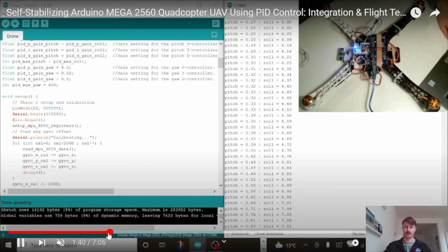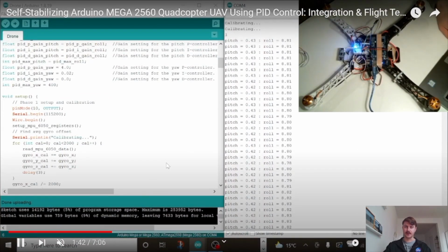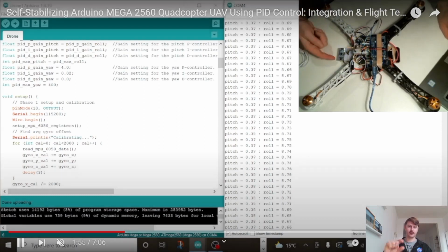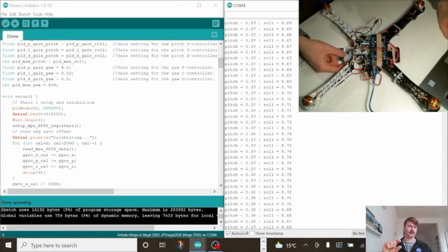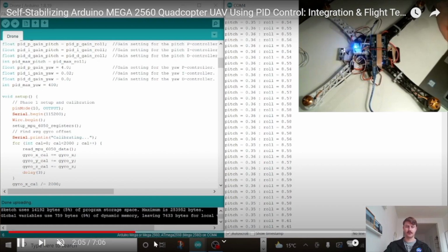We have also a little demo that I show up here where the distance sensor takes that first reading of the initial ground height, and I used inches instead of centimeters because inches is a wider measurement, so a little bit of fluctuation in its height wouldn't change that measurement, and that way once it reached it, it had a little bit of margin for play, and that was a good thing for the system.